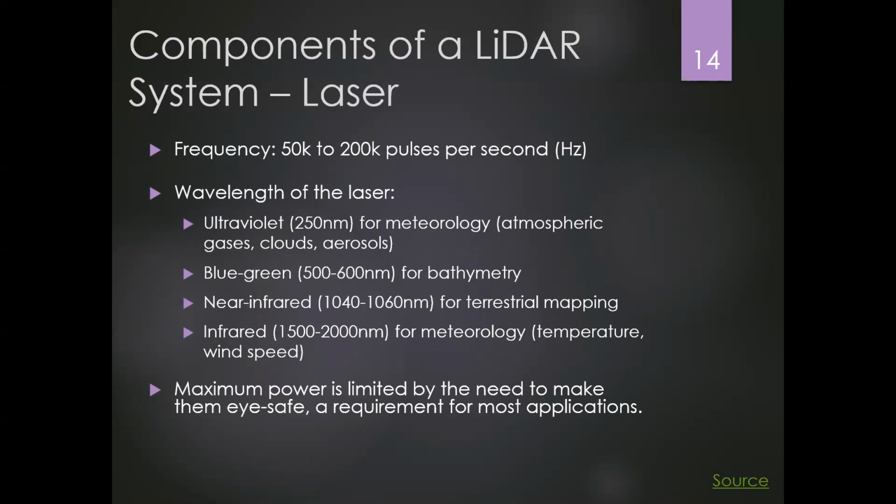You cannot see them, but they can still hurt you. So the maximum power of the laser employed by LiDAR systems needs to be limited to a specific range to make sure that even though people cannot see those LiDAR pulses, they're still safe if you accidentally look at them, okay?